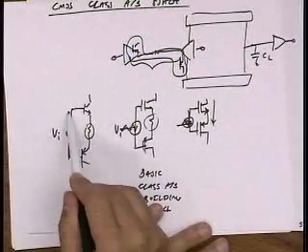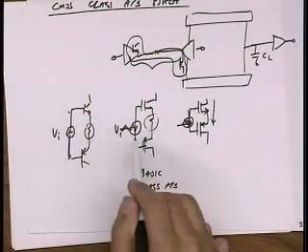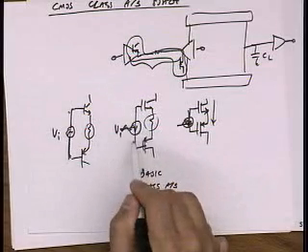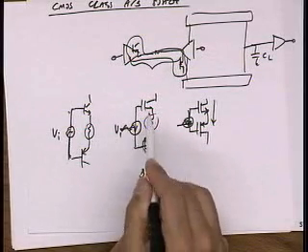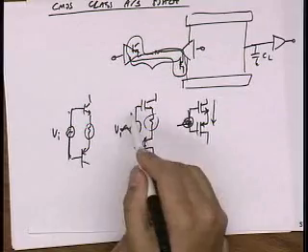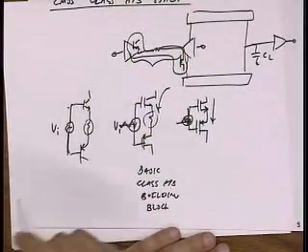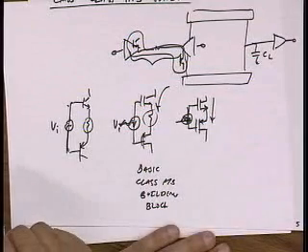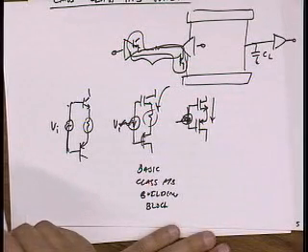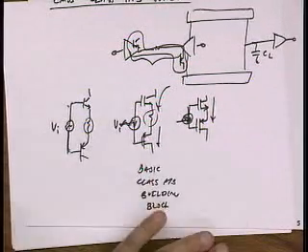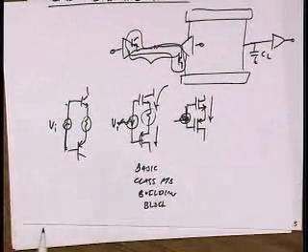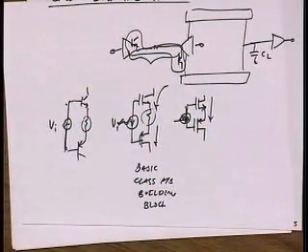So I'm really applying my input voltage across this resistor. In a MOS version, I apply my input voltage across these two VGSs. If the input is positive, I draw current from this side, right? If the VGS is negative, I draw current from the opposite transistor, right? So I can both source and sink current. Okay, questions?